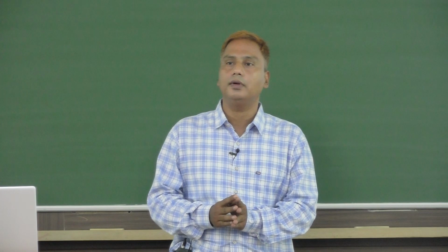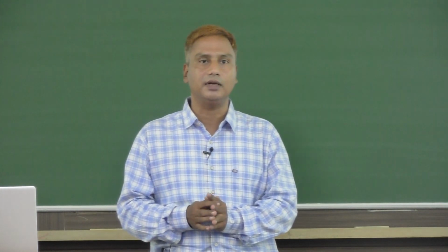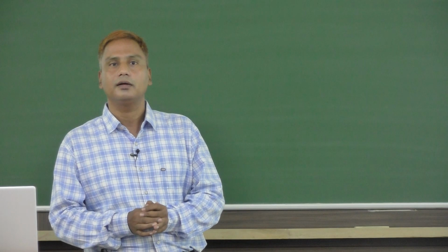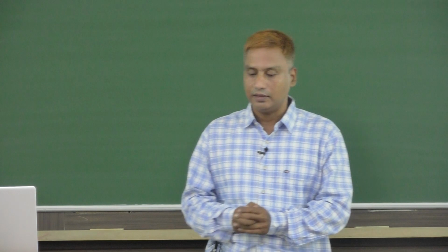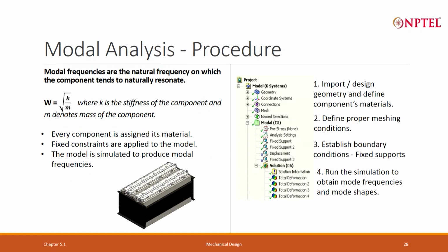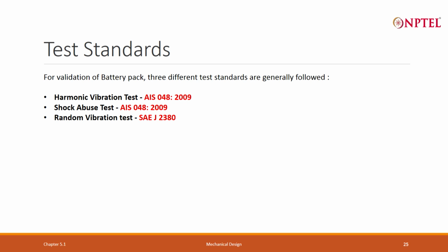Next we defined free vibration and forced vibration. Then we went through the different standards we use in India, AIS 048 and one SAE standard, J2380. We did a case study of the 60 volt battery pack we were designing, where we looked at the modal analysis, deformation and maximum stress, and with that we ended our mechanical development.